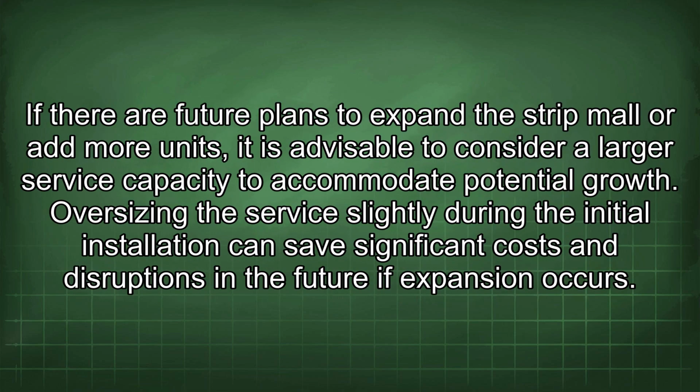If there are future plans to expand the strip mall or add more units, it is advisable to consider a larger service capacity to accommodate potential growth. Oversizing the service slightly during the initial installation can save significant costs and disruptions in the future if expansion occurs.